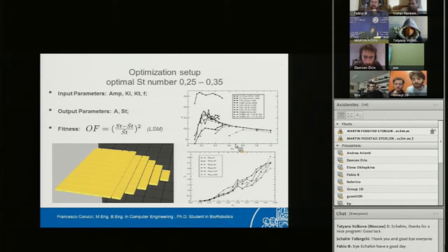They are very important. The one on the bottom is the Strouhal number versus a thrust coefficient that is proportional to the thrust. So this allows, at a fixed Reynolds number, to have the thrust just knowing this Strouhal number, that we can take from our model using the frequency of actuation, which is for us a parameter, and the amplitude of waving of the bottom boundary. And the top one instead is the efficiency of swimming. This is even more interesting.